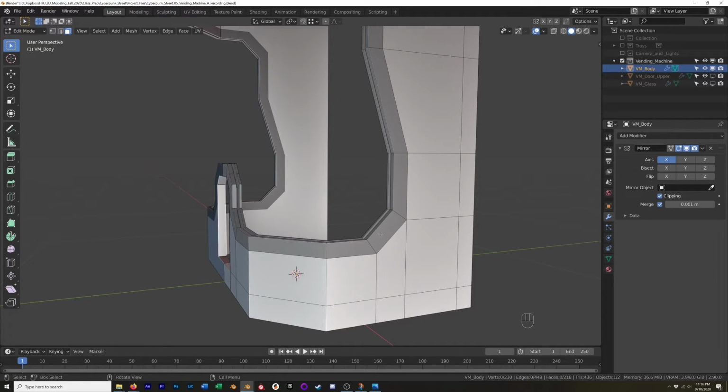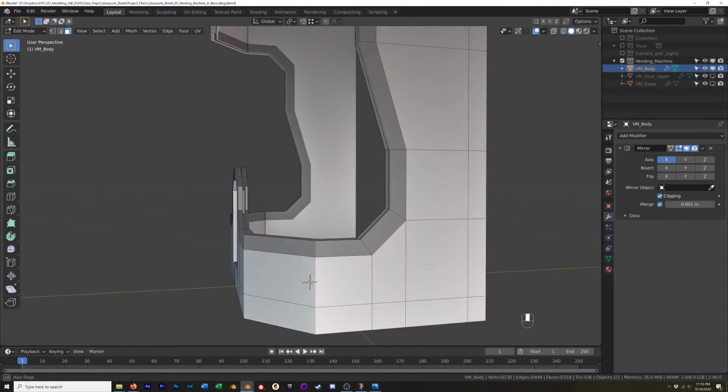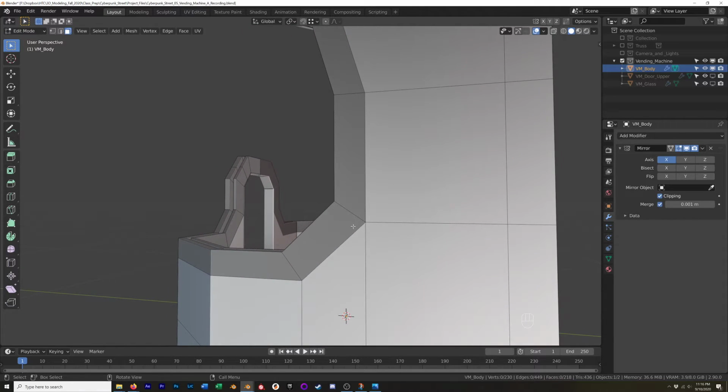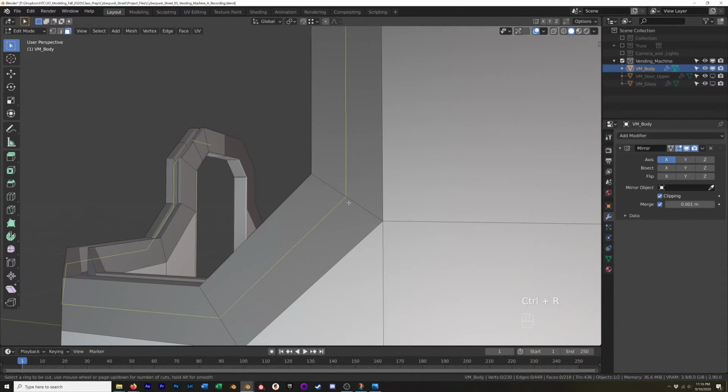A couple things left to do here. We have those insets and we have this extrusion here. So let's do this rim extrusion next. And the first thing I want to do is add in an edge loop right here, and E to keep it even, and make sure that it's snapping to the outside here, where the little red dot is on the outside of the rim. If it's on the inside, you can just hit F, and it will snap to the outside.